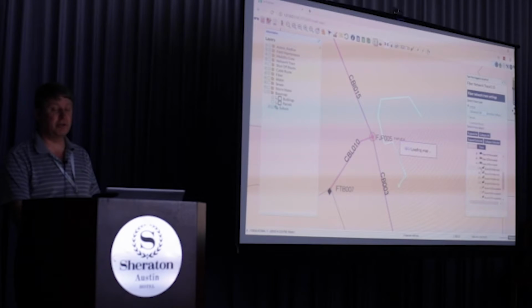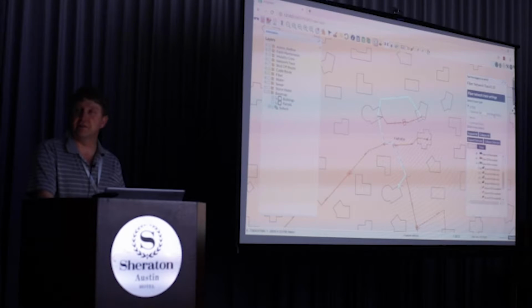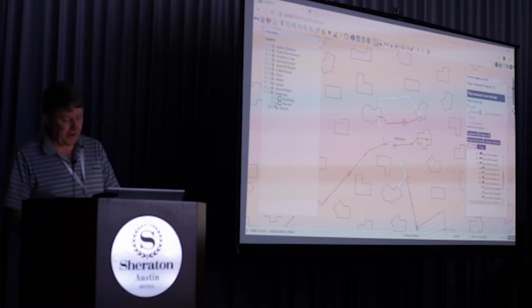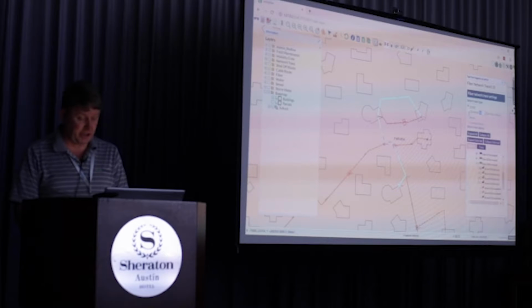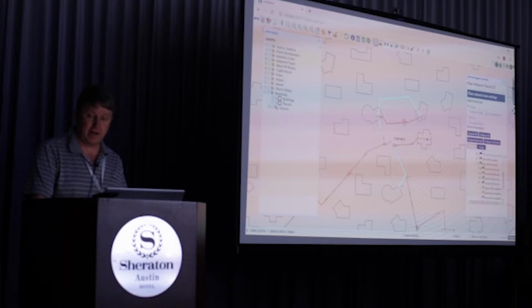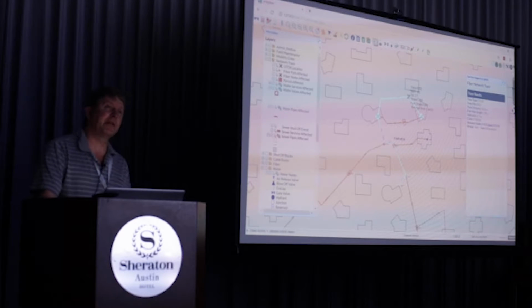So we're going to shine light down that particular strand. And what it will now tell you is that on this particular strand, the maximum length is 190 meters that it could go through. And your device is saying, let's do that, you've got 165 meters from here, you've got the break, and let's trace that down, and it will then tell you that, okay, that is the distance. You've got a tolerance there.